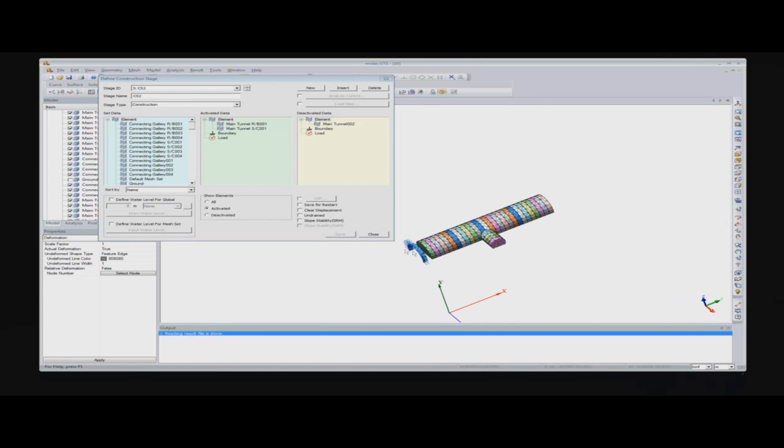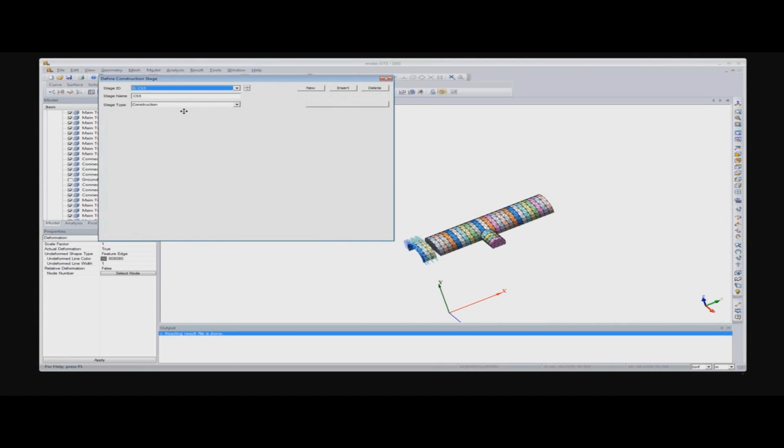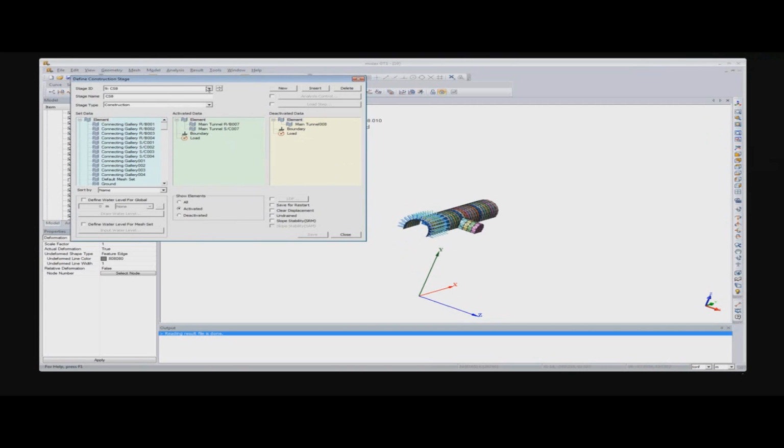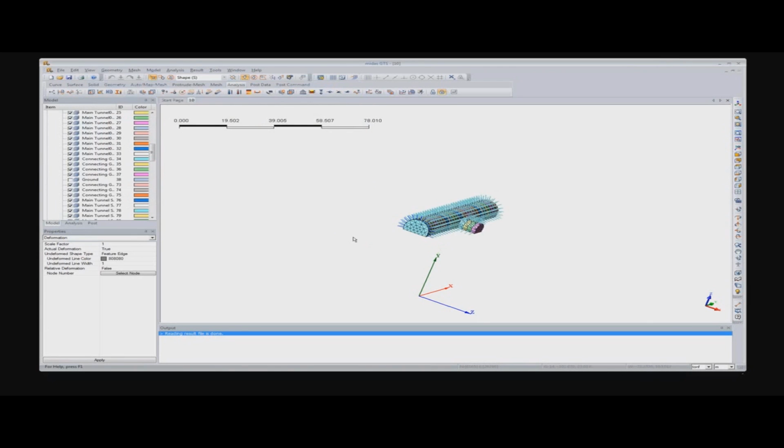And the first shotcrete is created, placed there. Same thing going on, excavating and then adding this shotcrete with these rock bolts. So the same thing going on, and as I mentioned, anytime you can change the construction stages. You can add or delete these boundaries or loads or anything that you are interested to change. Okay. And then performing the analysis and getting the result, because the result takes time. I don't want to take your time for that one.